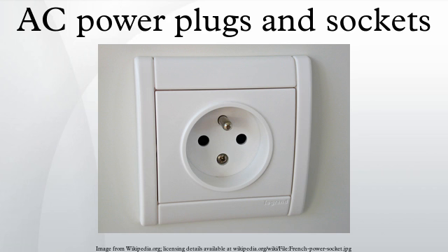Some of these sockets have one or more earth holes to allow 3-pin plugs. On properly wired circuits, the earth contact will be connected to earth. However, they cannot provide earthing to all types of plugs, as is the case of Schuko and French plugs. Those designed to accept British plugs have pin apertures which are larger than allowed by BS 1363, and are therefore not legal for UK or Irish use.